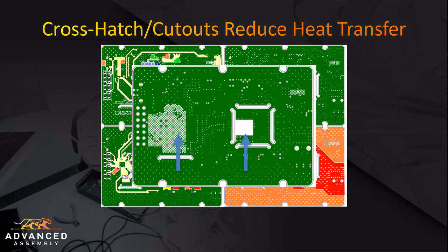So secondly, this is kind of the fun one, and this is the one that I feel a lot of people kind of overlook. If you need to protect a really critical part, you can actually create a clearance and just make basically 3 to 4 sides around it using just enough copper to run your power and signal traces. So what you're seeing in the area that's arrowed, the white is obviously the clearance. And so the component that's going to be placed on that footprint right there, if there is a sensitive part to that component, you can clearance that, still maintaining total connection to the rest of the ground artwork, but you can leave that area free and clear so that that heat is not going to affect it.